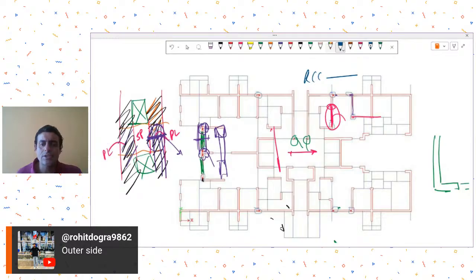So in such cases, check if moment releases are an option for you, and of course it has to be ensured that proper detailing is done on site also. So check if moment releases at the beam ends is an option, because anyway you have so many walls that there is an RCC structural wall system in both directions. So check that, maybe that resolves your corner nib problem. Okay, so try these things out and then let's see what happens.